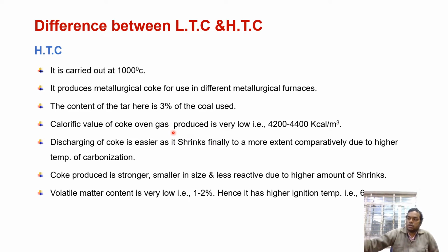Then here the most important aspect is that the coke produced in high temperature carbonization process is stronger and smaller in size and less reactive due to higher amount of shrinkage. Okay students, this is a very important aspect of high temperature carbonization.